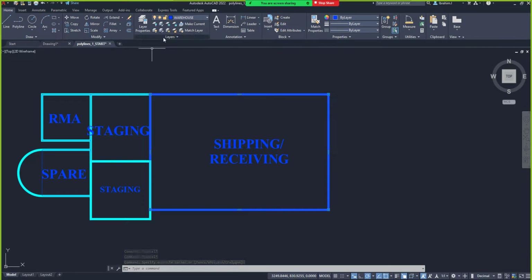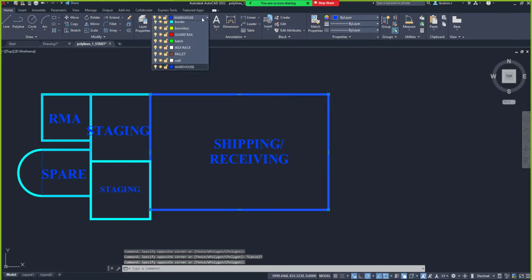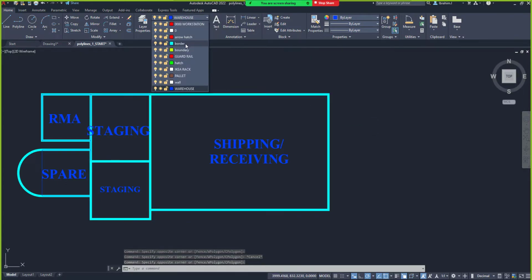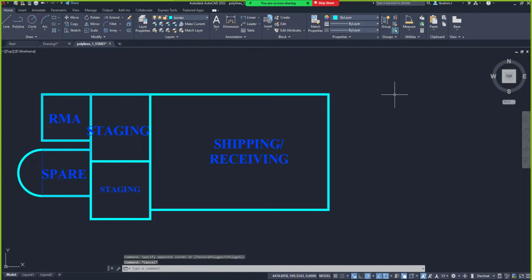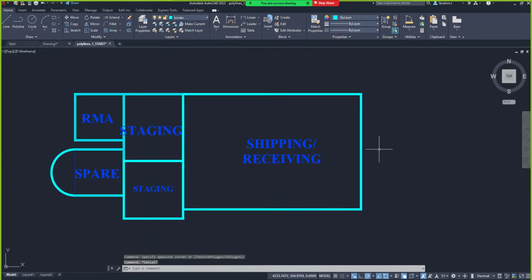This is the layer panel, right? We are not supposed to talk about this today, not at all. You understand? But because you asked that question, let me just quickly convert it. To convert this shape into this bright green color, I'll simply select the object on our workspace, click on this drop down and go to the layer that I want. And we are back. Is it making sense so far? Are we good to go?